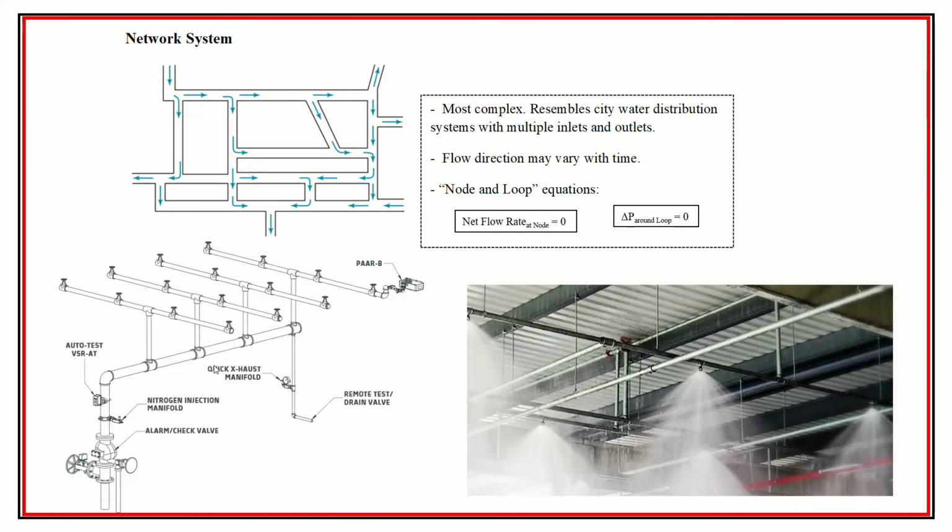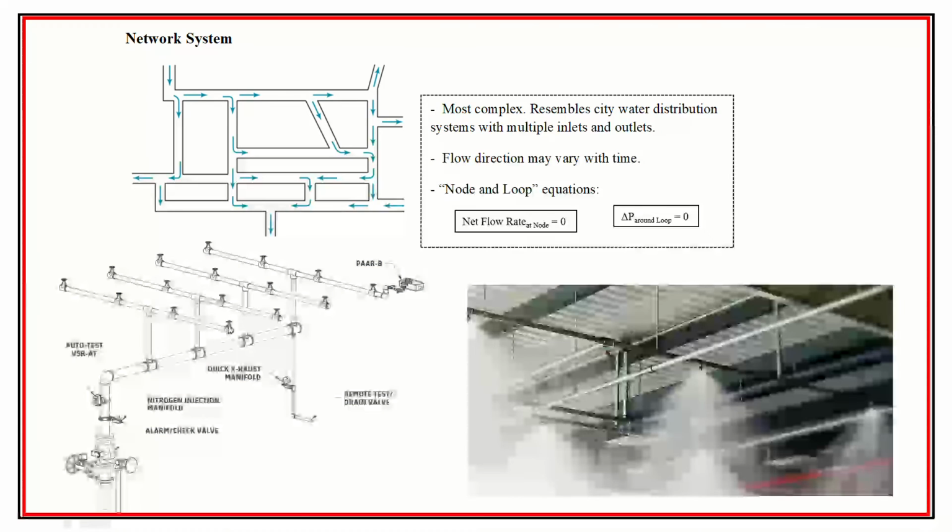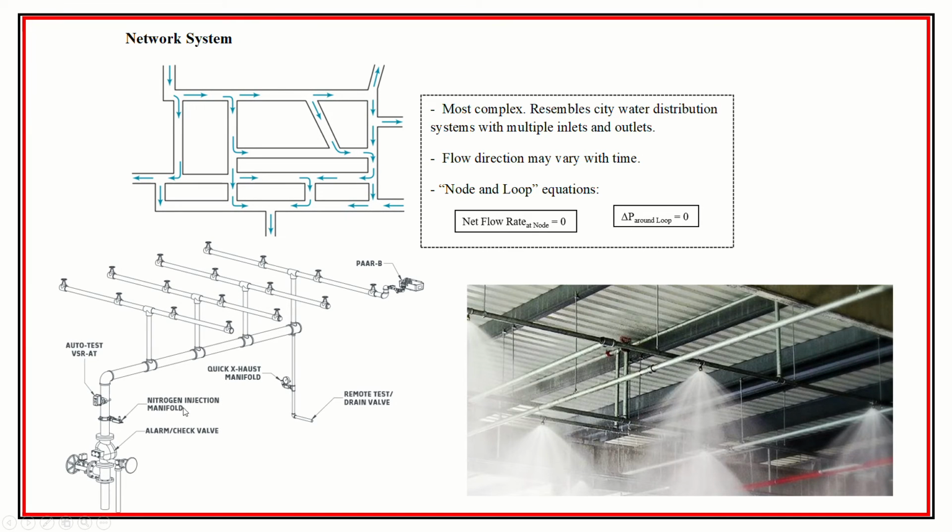We hired an outside group that had software that could figure out the piping diameters and arrangements to get the proper coverage for the sprinkler system, and some of the equipment that's required to make sure that it goes off in the right way. And some of them have compressed air inside, so when a fire reaches a high enough temperature, something melts or at least gets triggered inside the sprinkler, and then it goes off.